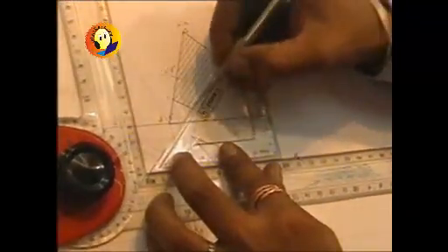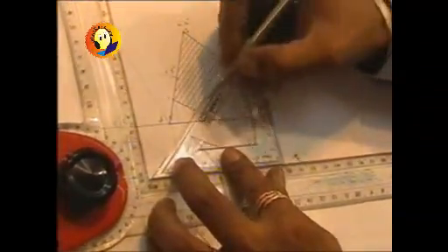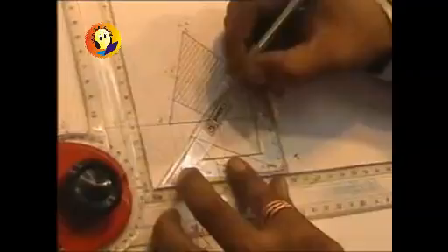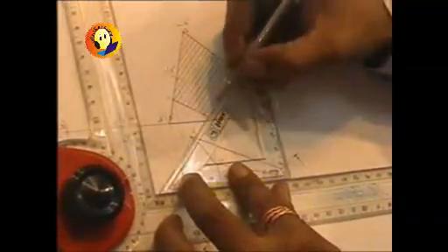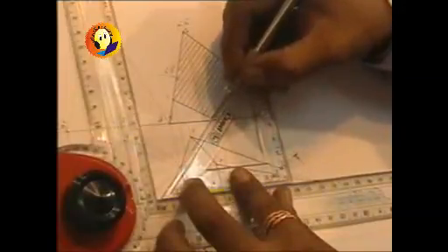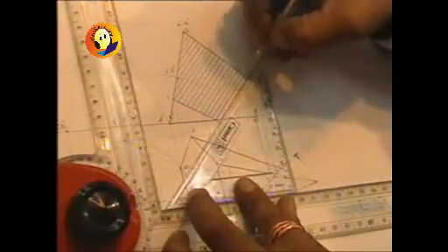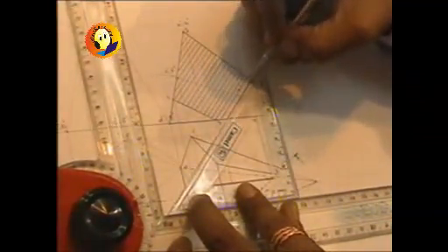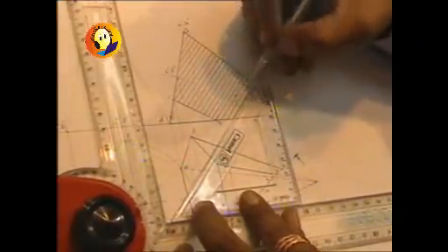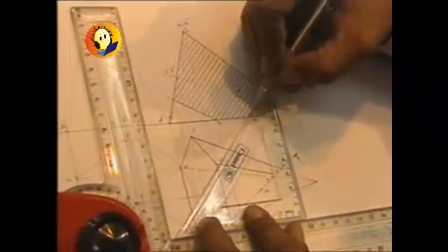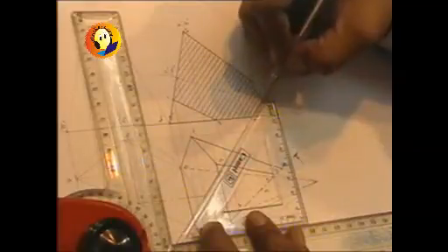Now whether these types of problems are asked in the exam or not, or whether these problems can be done in a stipulated time of 45 minutes is altogether a different issue, but the manner in which the particular hexagonal pyramid has been cut over here is very important, and is going to be one of the best problems available for the sections of pyramids given for the development job. So the hatching lines are shown in the front view, and now we are required to go for the development.